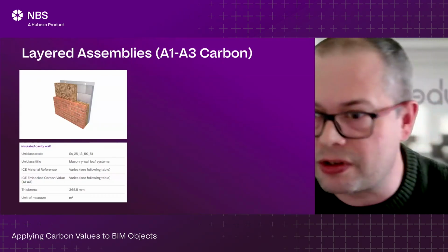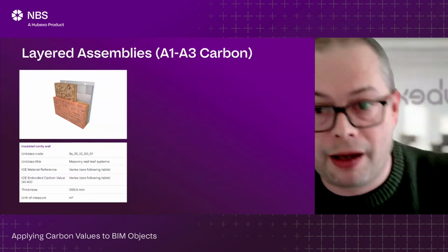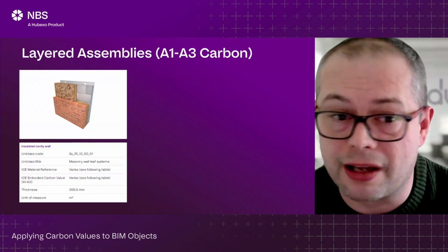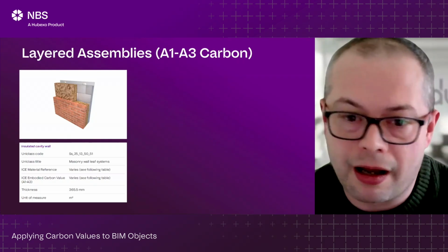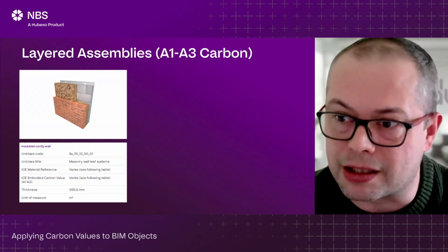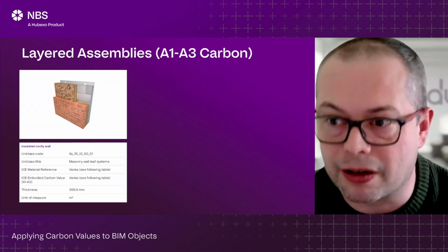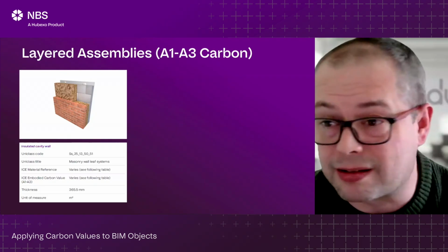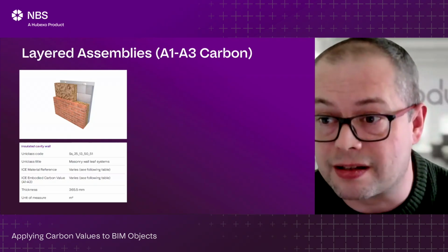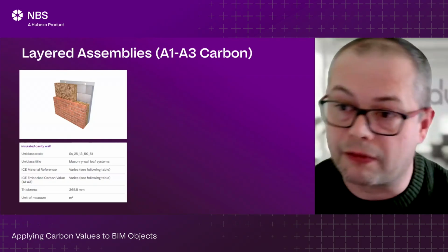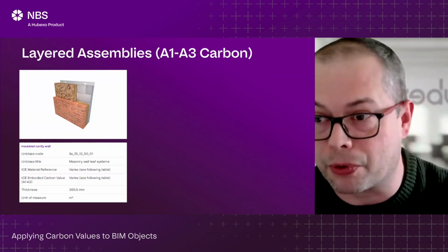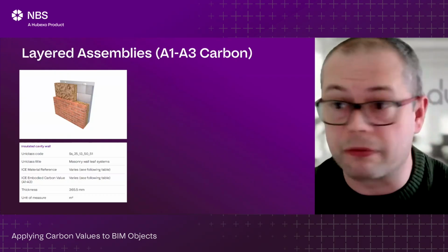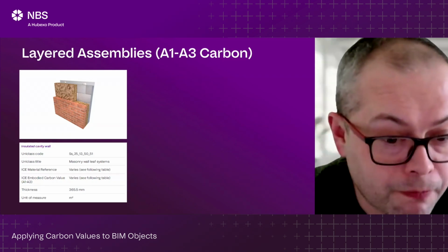I think if you want to keep reusing these data sets that you may build up, having them classified and structured is really, really key in terms of applying them to your BIM objects. Particularly if you're looking at ISO 19650 and the BIM framework there. Uniclass is referenced as the classification system for applying to these things. So if you are wanting to apply values to your project, it's a good starting point, and then you can build up these data sets that can be reused time and time again.